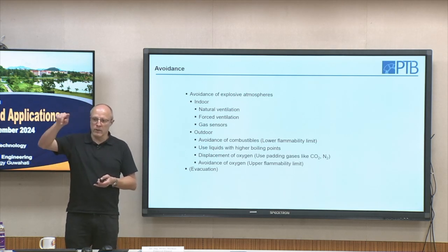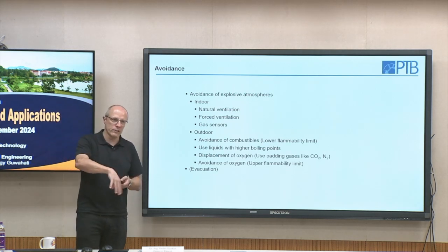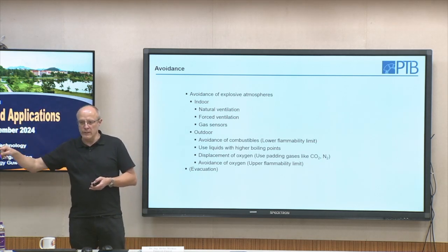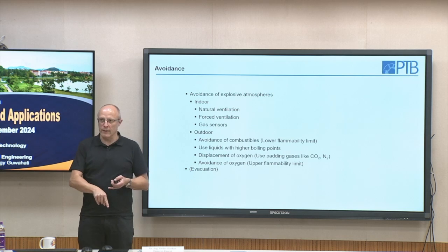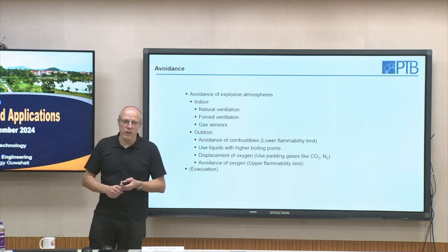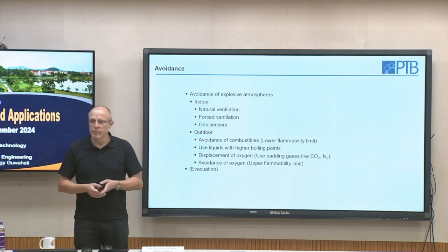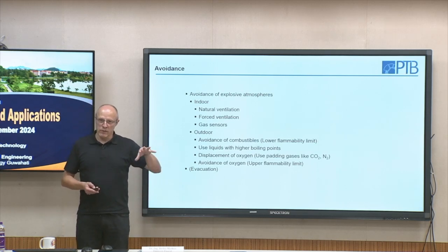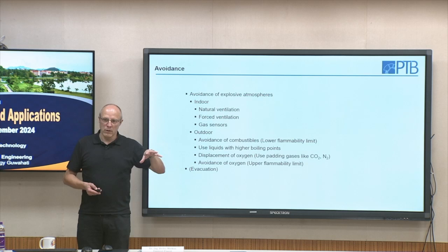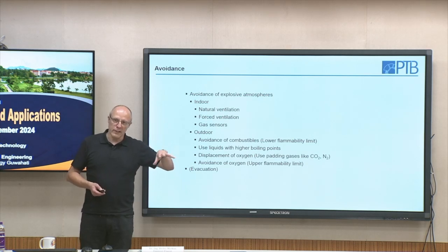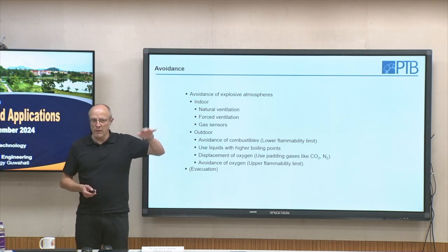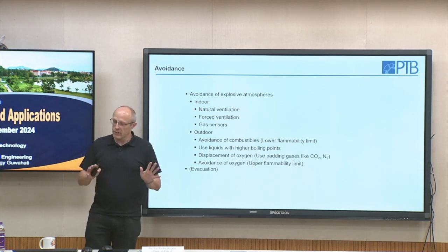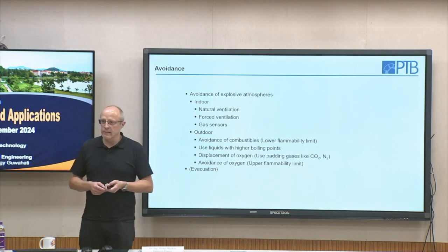You fill a tank on land with the oil or gasoline from your ship, and then the atmosphere from the tank is going to your ship tank, so that there is no leakage of hydrocarbons to the outer atmosphere. So inside your ship tank there is now no liquid anymore, but a very rich mixture of combustible in air above the upper explosion limit, so it cannot burn. Safe concept until you have an accident.